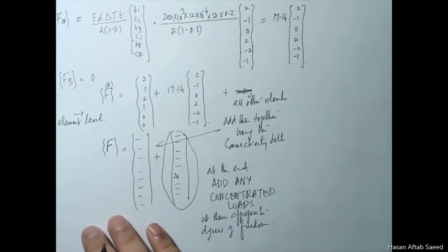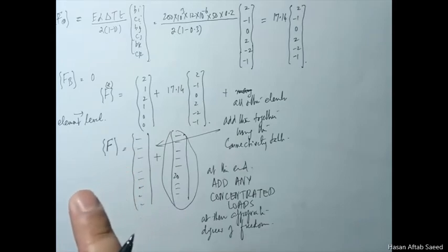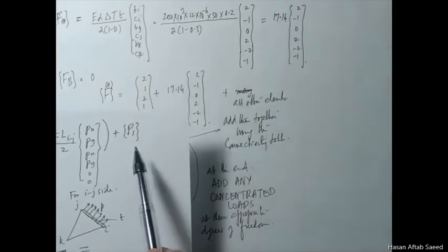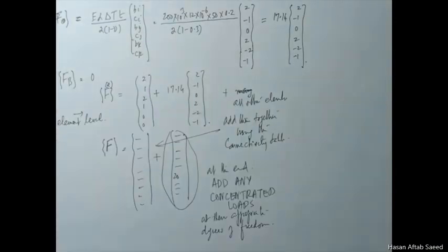And after the assembly, that is, all the K matrices will be assembled together, this part, and at the end you will add the concentrated force vector, and then you get the right hand side completed. Once this is done, obviously you apply the boundary conditions.